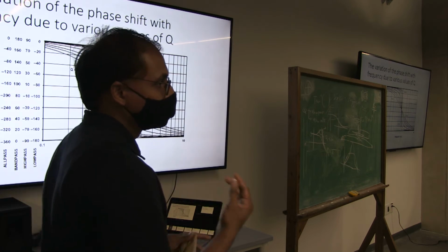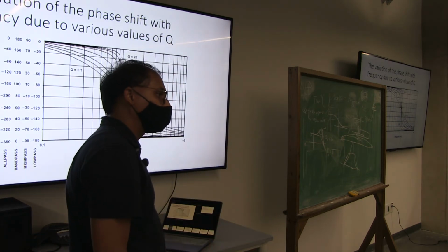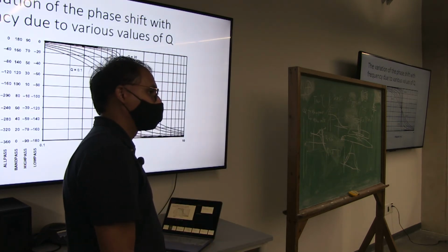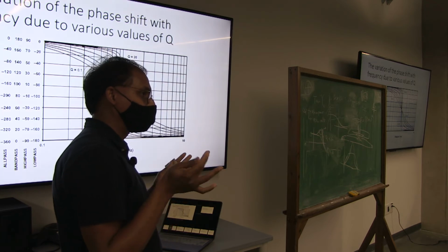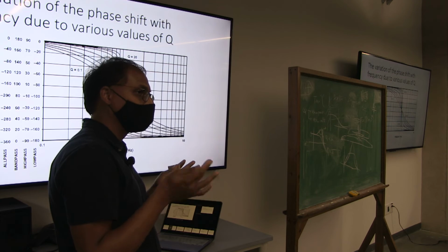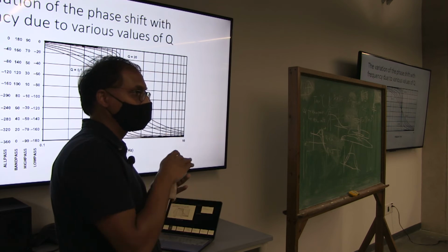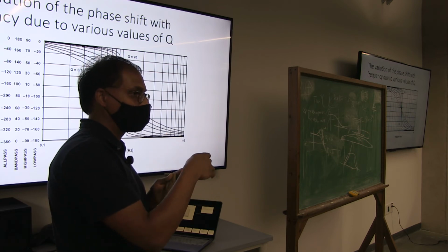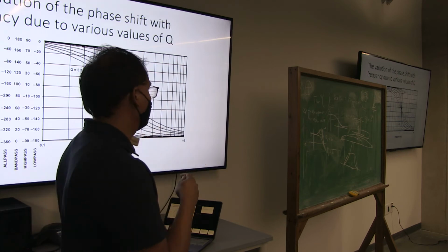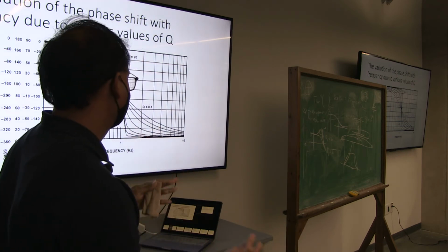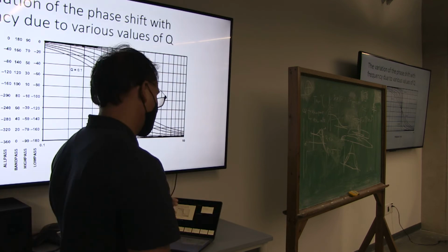And that will give us tan inverse omega by q for the first order. So as long as you're comfortable with converting Laplace transform and calculating the phase response for a transfer function, this all should be implications of writing the transfer function.